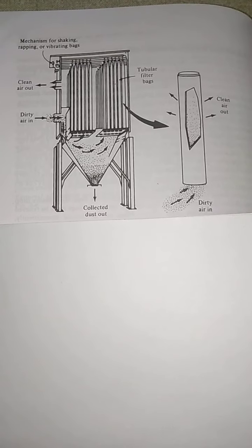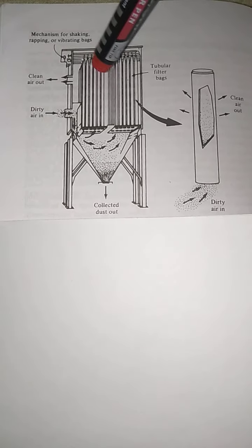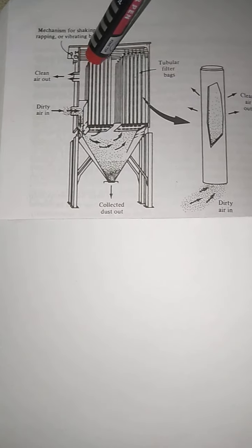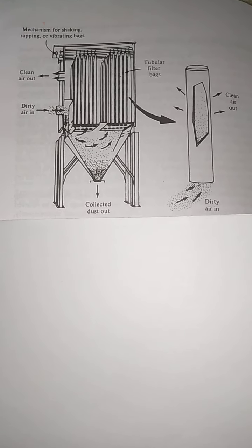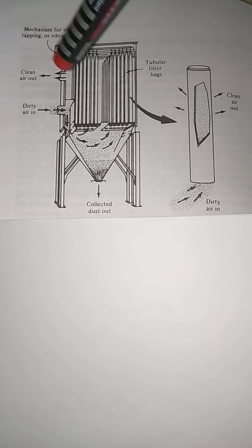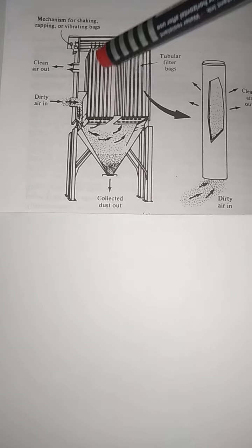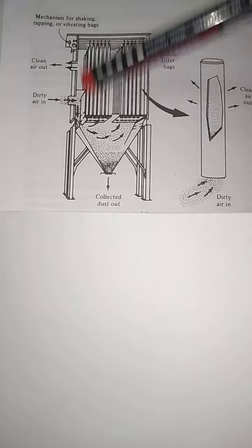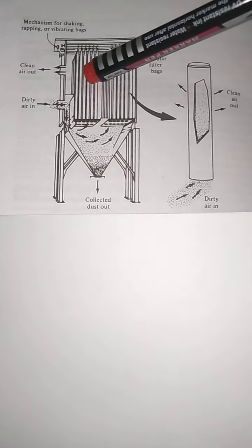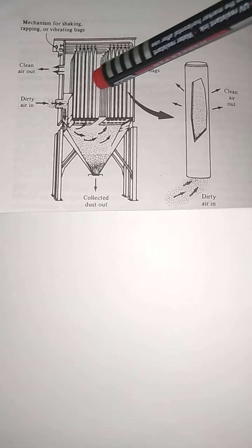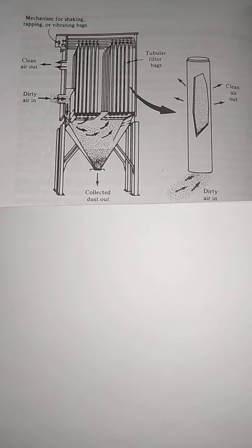Now maintenance is also going to be required in these filters. If these filters are clogged, they cannot clean the polluted gas, so we require maintenance work. So how are we going to maintain it? We are going to remove the suspended particles which have been arrested in this fabric. We are going to clean it by the process of rapping, shaking and vibration, and by reverse airflow.